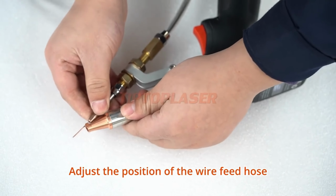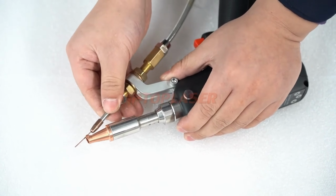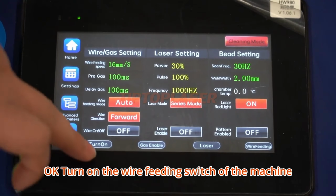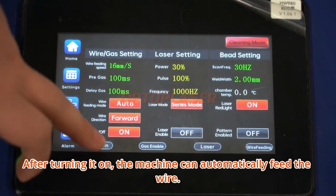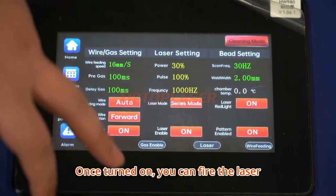Adjust the position of the wire feed hose, convenient for subsequent wire drawing. Okay, turn on the wire feeding switch of the machine. After turning it on, the machine can automatically feed the wire. Once turned on, you can fire the laser.